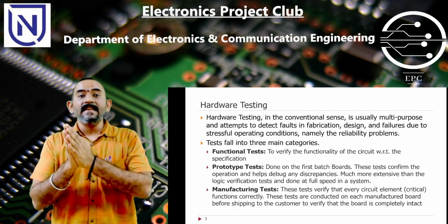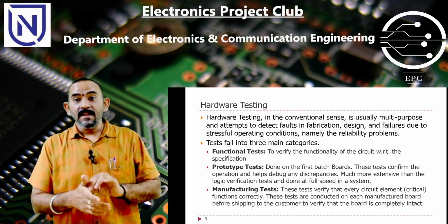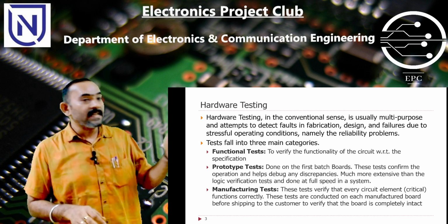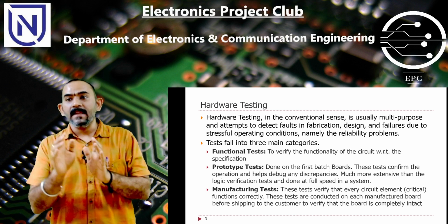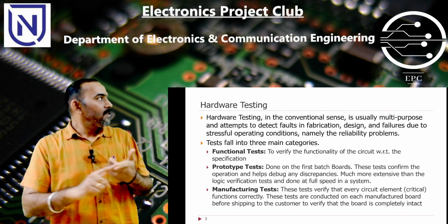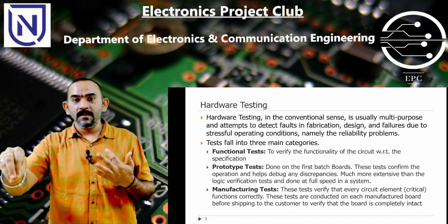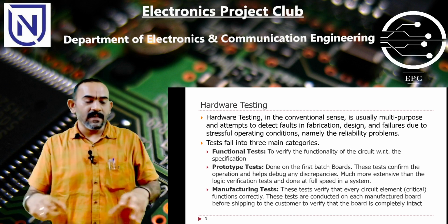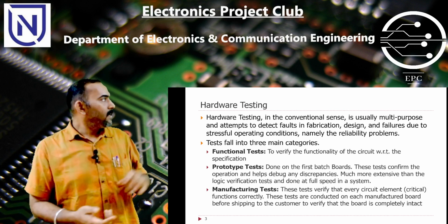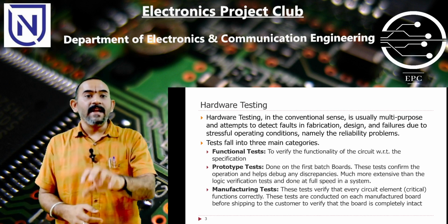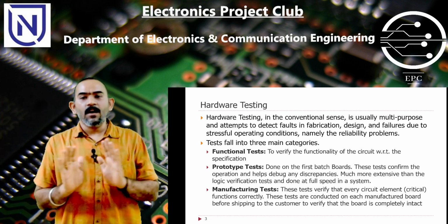Hardware testing basically is a multi-purpose function whose main purpose is to detect faults, and these faults can happen in different life cycle areas. That is, it can be in fabrication, or in the design, or it can be failures due to operation. When you are operating the circuit, the stressful conditions you make the circuit work at can lead to a fault. Basically what we are trying to find is issues which can cause poor reliability. That is the main thing of hardware testing.